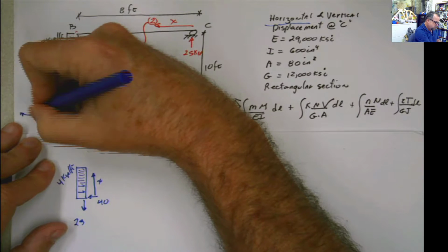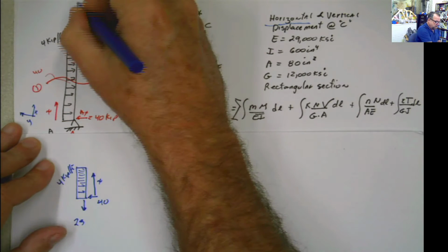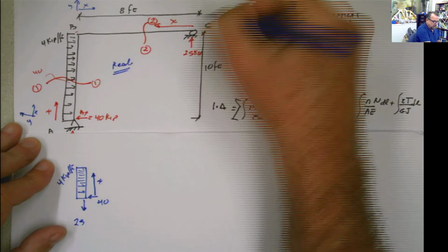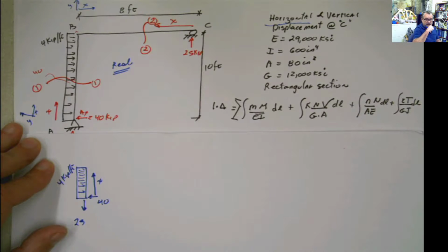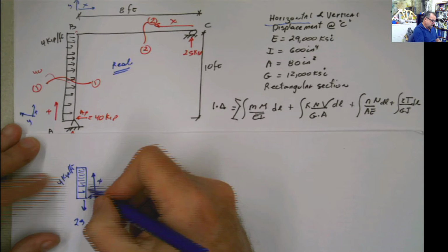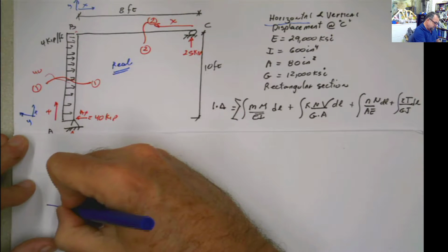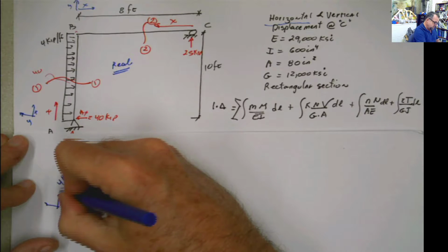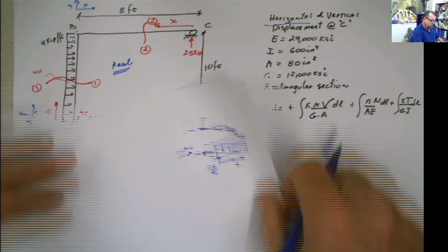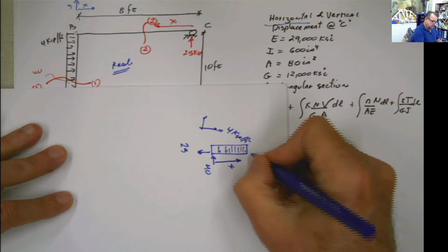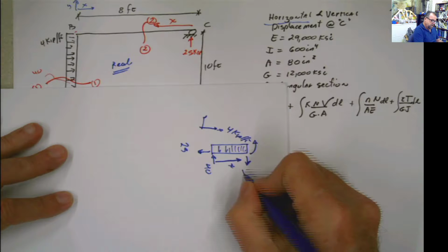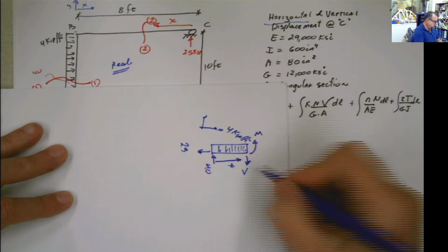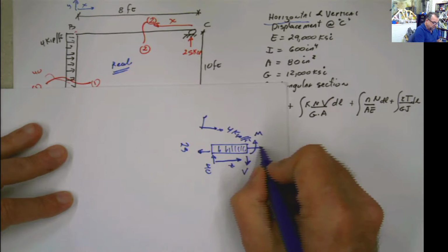I always do this xy, and then I go here and I go xy, and then if I have another leg here, I go xy. And depending on that, I have to be consistent during the whole problem. So I have that part over there, and if I follow this system, then I could do something like this. And then I can put my moment here and my shear here, because those are the positive accepted conventions, and of course the normal is going to be here.